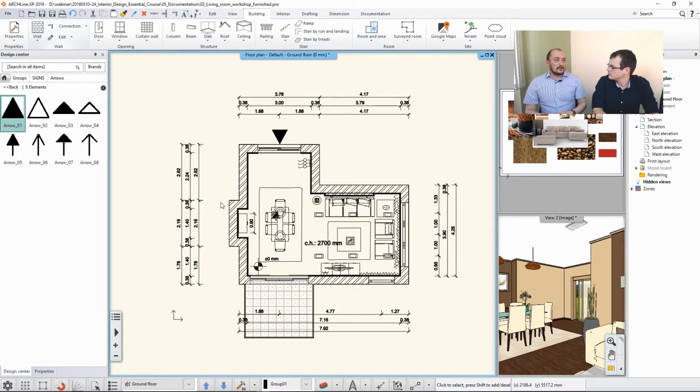Mostly we recommend to separate things, now we are talking about interior design projects, onto layers by room names. So for example, I should have living room furniture and living room decoration, for example living room curtains and things like that, living room lamps. At least these 3 or 4 packages you should set up room by room.